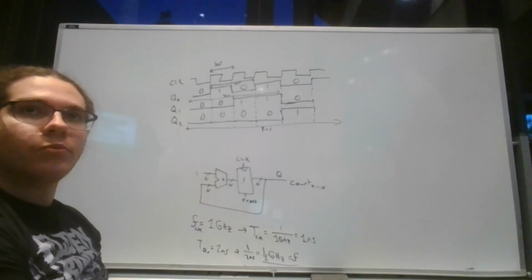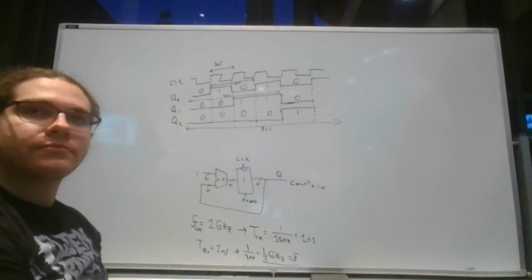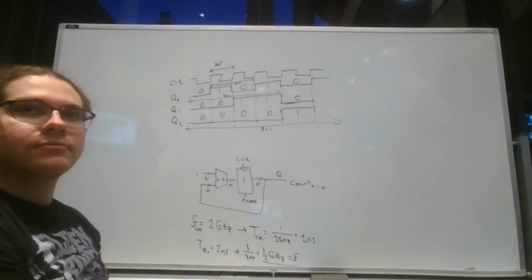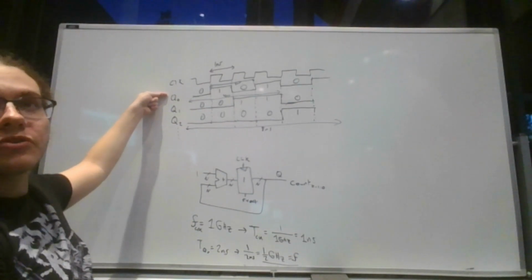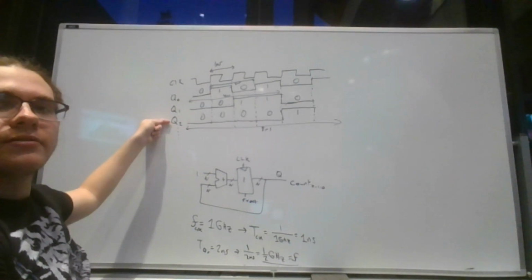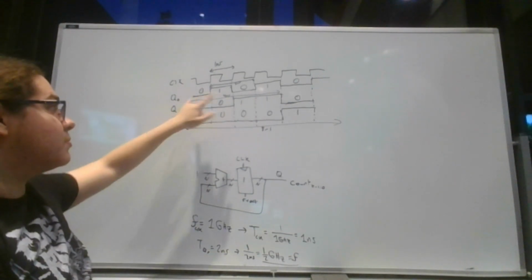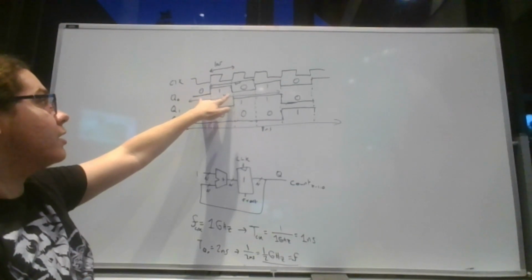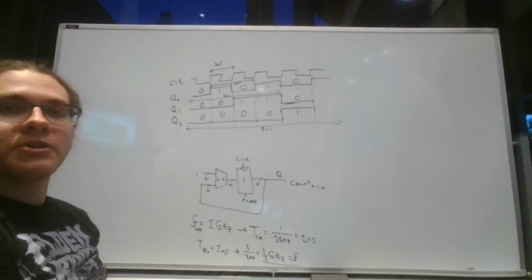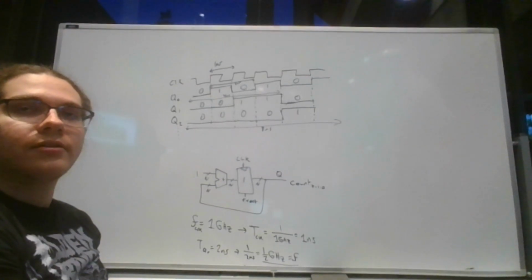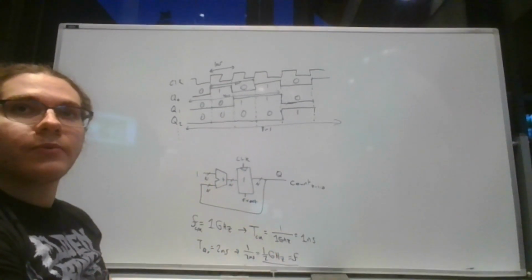So they're synchronous. One's derived from the other. We can treat these as clock sources if we send them to other bits of logic. All I'm saying is that it's periodic, and it's periodic specifically with respect to the original clock. It's derived from that original clock. And so they're synchronized in that sense.